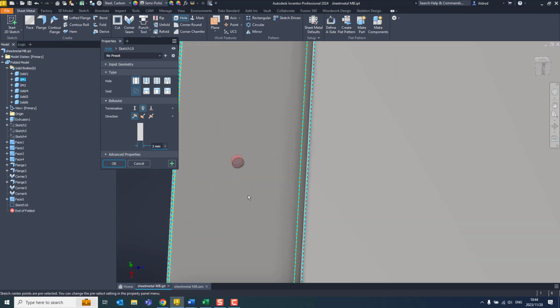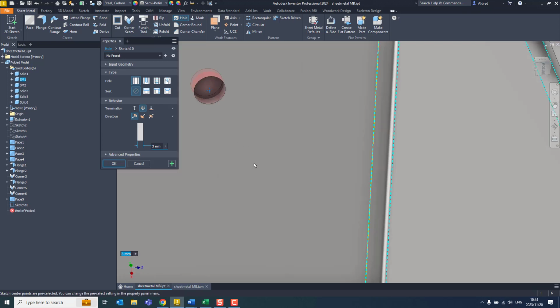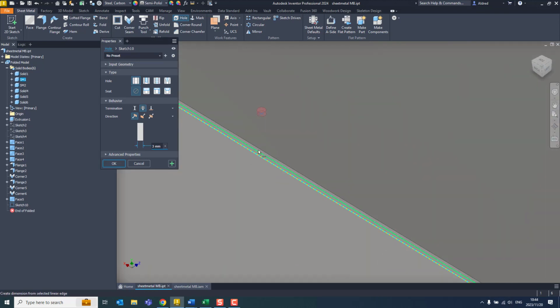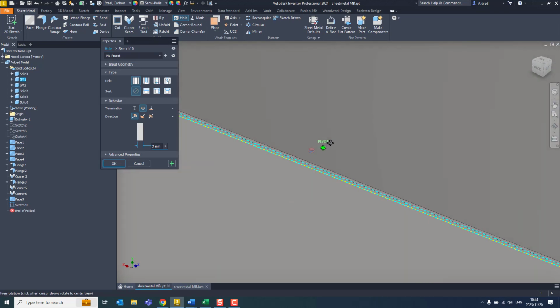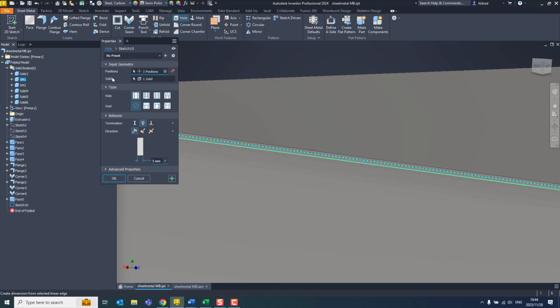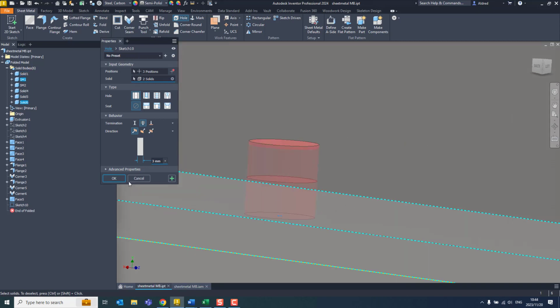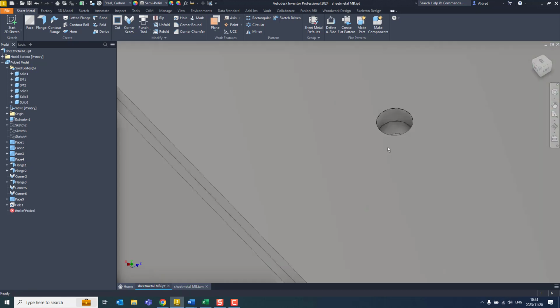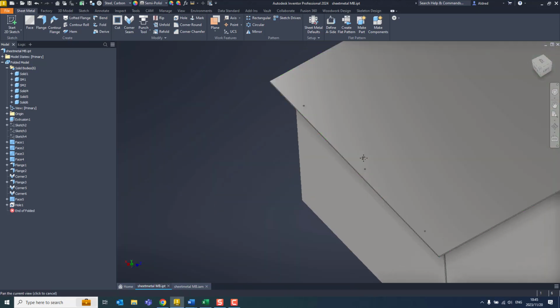It'll pick up all 3 components, but now what it's telling me is that it's only going to cut through the one part. So what we can do over here is, if I go to my input geometry, you'll see there it's cutting through one solid. I can select this, the top face, and you'll see it cuts through both of those. Okay. So now we know that our holes are placed exactly where they should be for both those parts over there.